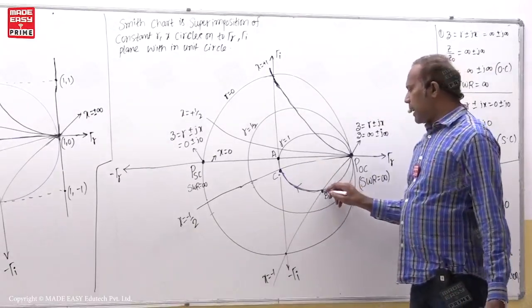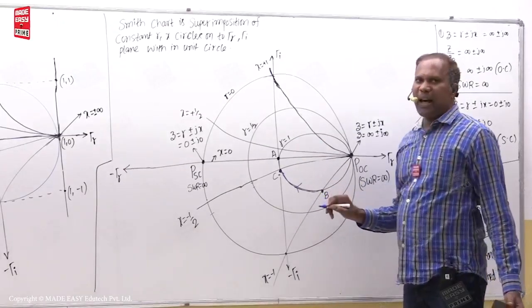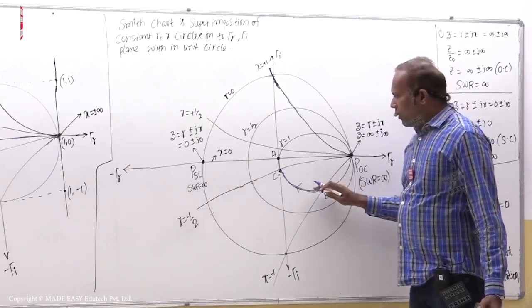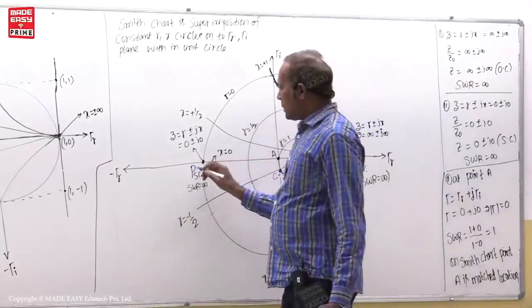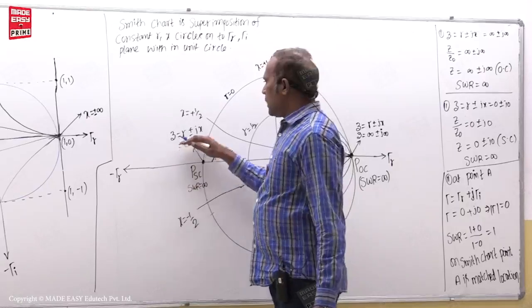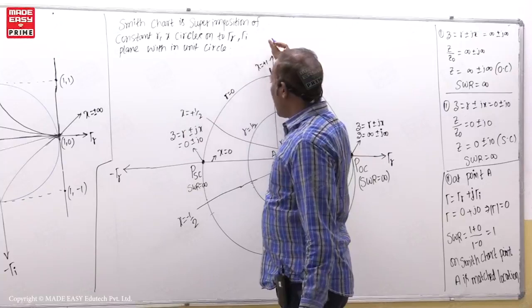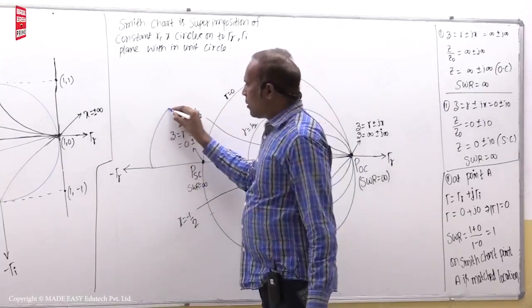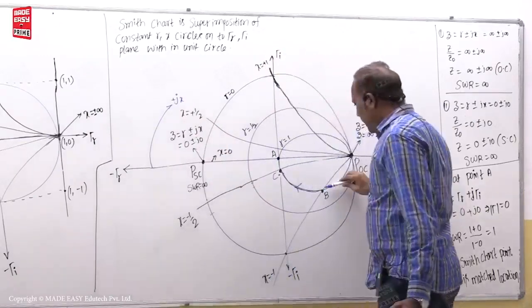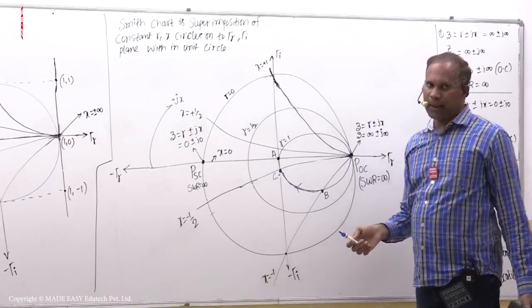That means you are going on a constant resistance circle. Resistance is a series parameter. And if you go upwards like this, here the x value is j0, here the x value is j1/2, here the x value is j1. So going like this, it is plus jx, and going upwards means the inductance value is increased. Inductance is also a series parameter.